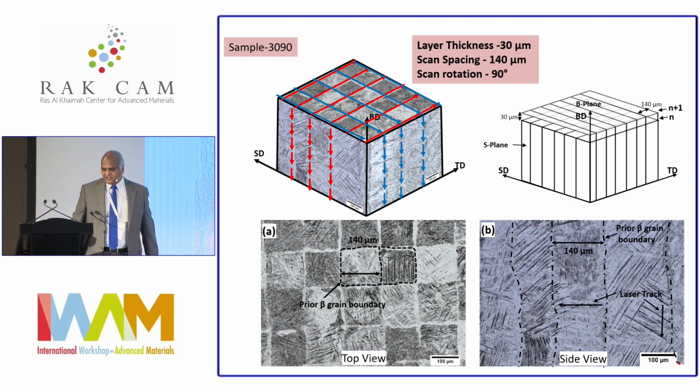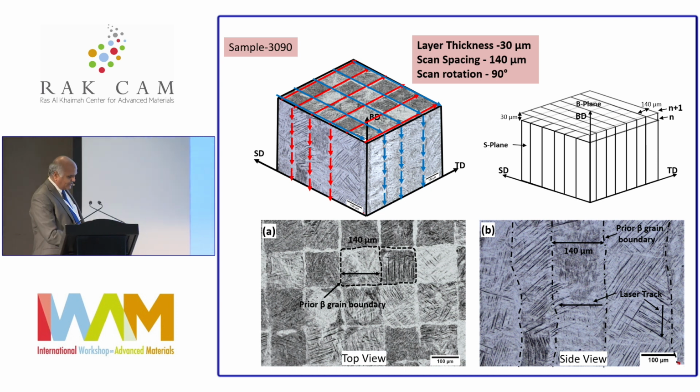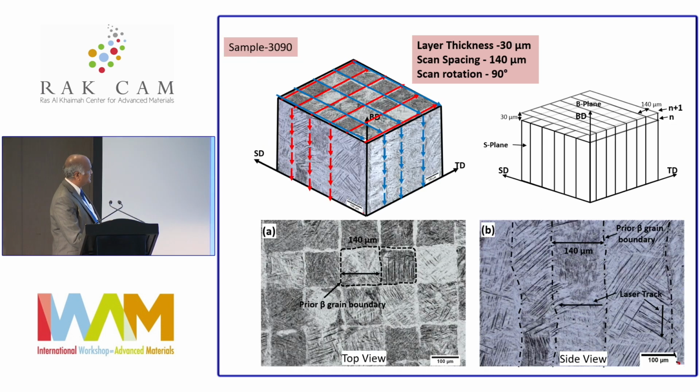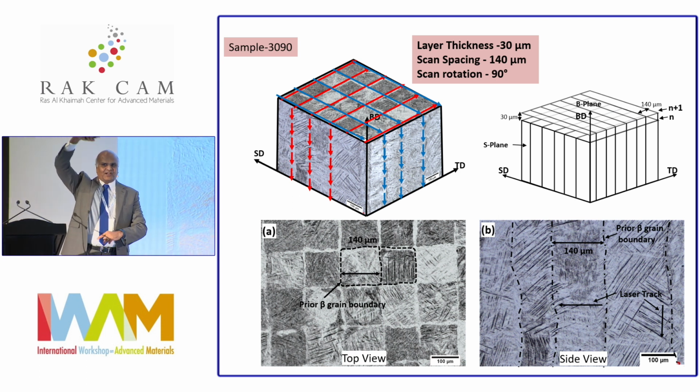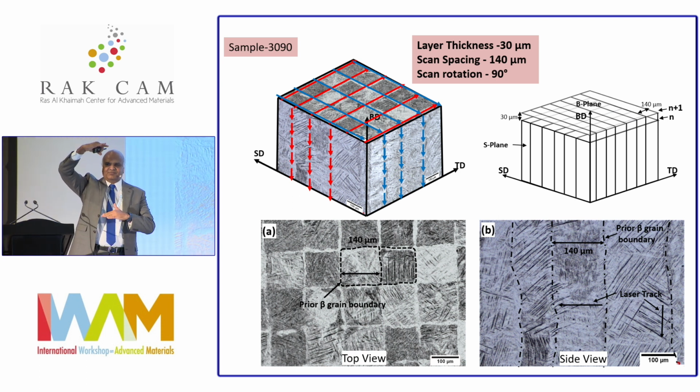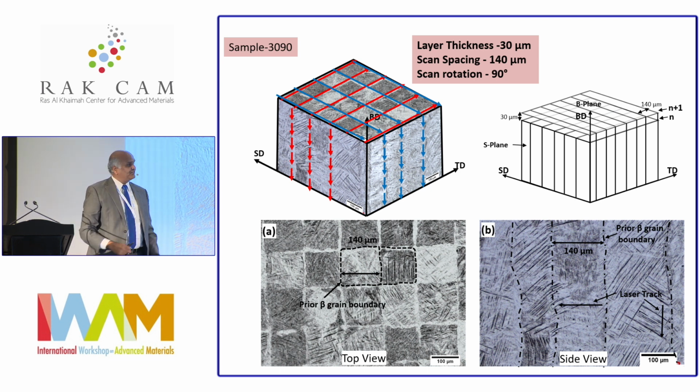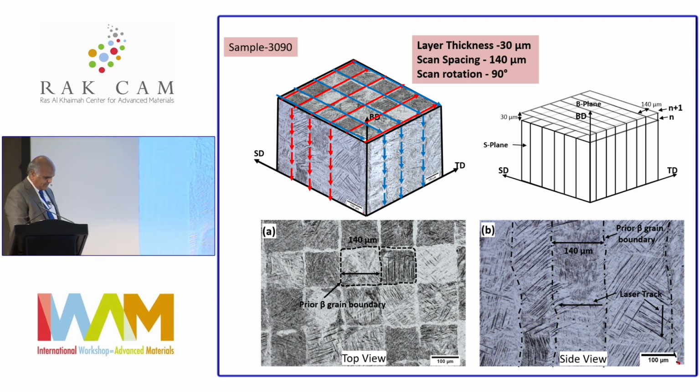So the epitaxial growth occurs. As a result, on the side, you get columnar structure. Whatever the build height is, essentially it is like taking square cross-section bricks, which are as high as your build thickness, and stacking them together, right?